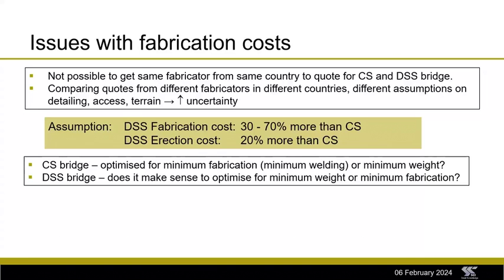Why? Well, a few reasons. You need a dedicated fabrication area, higher standards of cleanliness. Welding is a bit trickier with duplex because you have more movement, more spring back, and you have to tightly control the temperature during welding. So there'd be extra costs for preventing distortion or correcting them. You have to use non-carbon steel tooling.